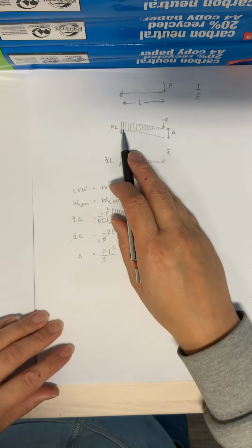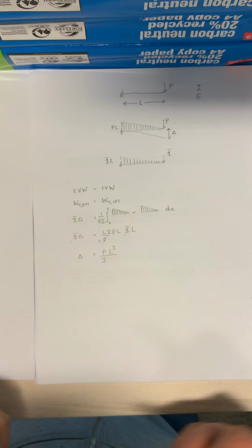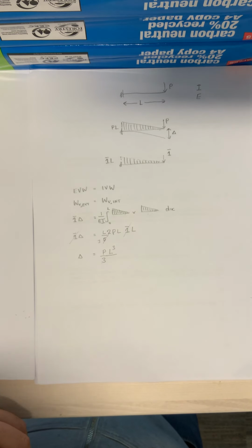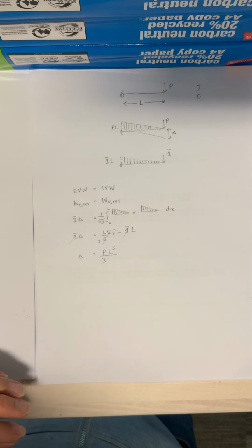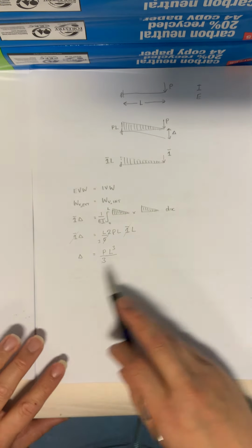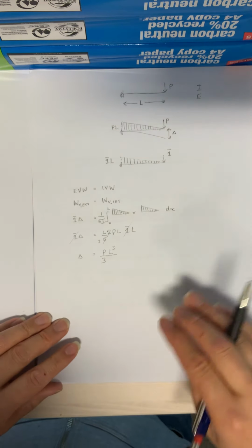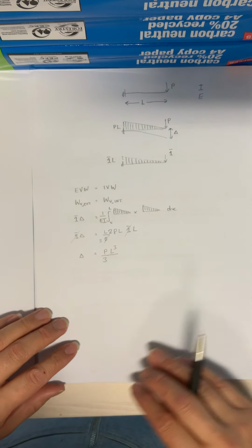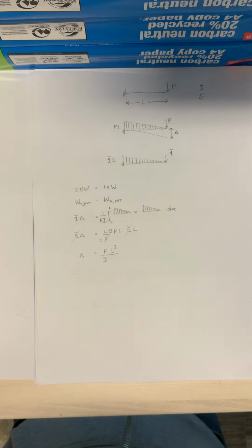If it was sagging multiplied by sagging, then it's the same and it is also positive. But when you've got hogging multiplied by sagging, then whatever you do for the integral will turn out to be negative. So I just mentioned that at this stage to explain where the sign convention is going to be coming into it.